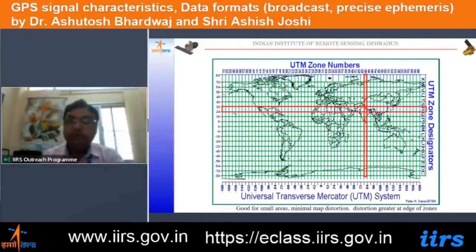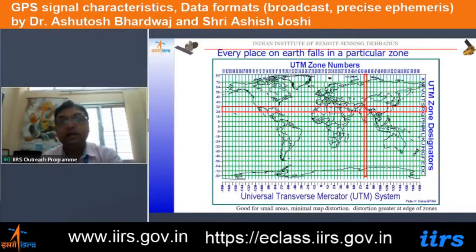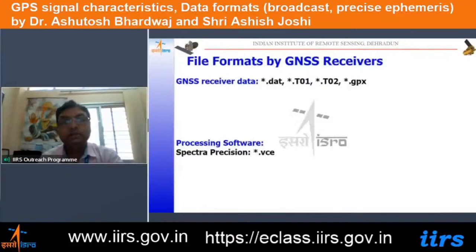So the best way is that you can do this task later. First you can do the survey in geographic lat long itself. After processing and mapping time, you can change the UTM zone number. So projections can be changed later also.